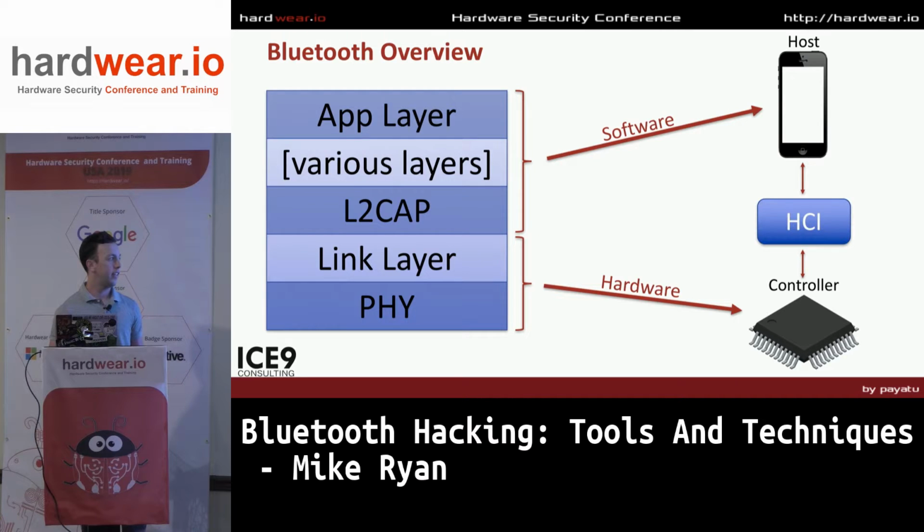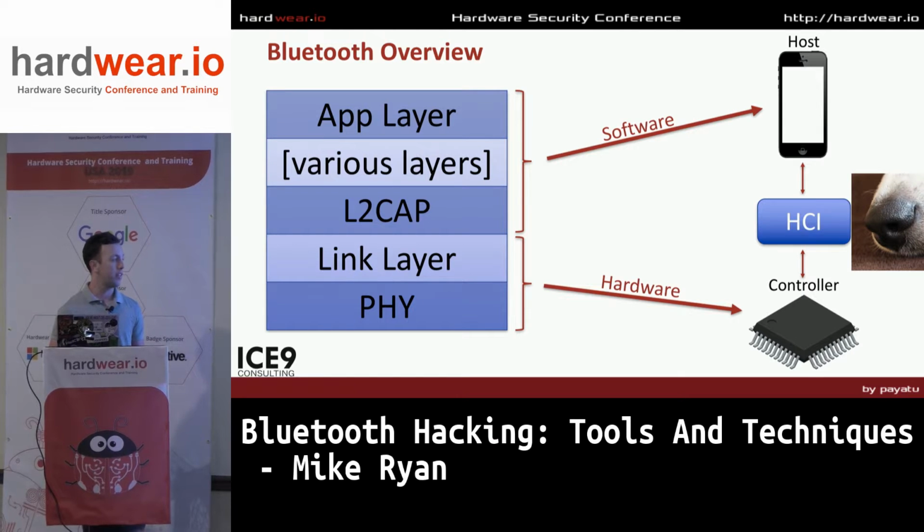The way the host communicates with the controller is via an internal bus, and on that internal bus, they communicate using a language called HCI, the host controller interface. This is where we're going to sniff. And the power of this is that we're sniffing the data while it's still on the device, meaning we're going to capture 100% of the packets, and as a bonus, the protocol level encryption happens down here.